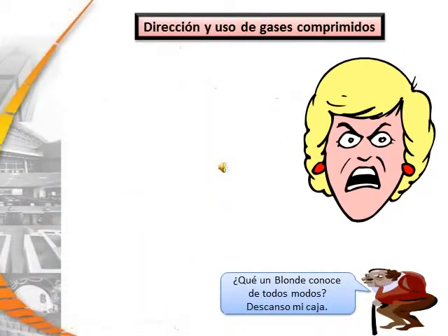Some valves may require washers. This should be checked before the regulator is fitted. Only wrenches and tools provided by the cylinder supplier should be used to open or close the valve. At no time should pliers be used to open the cylinder valve.